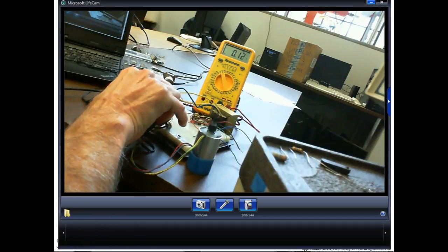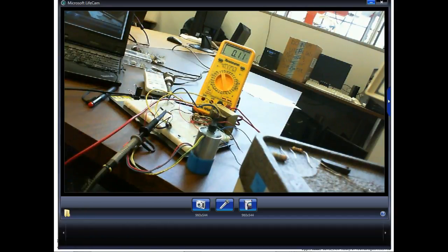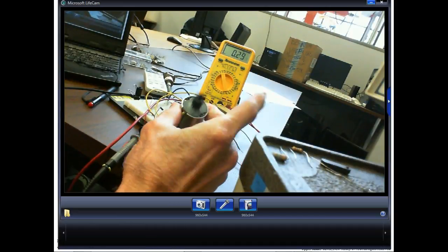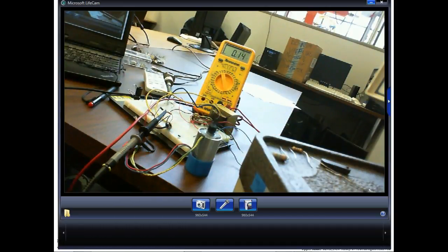It tries to. By the way, we got a motor called a universal motor. Guess what a universal motor will do? It'll run on AC or DC. It's a series motor for some reasons we're not going to talk about. But look here, that's running real nice. Make sure I have a 1 amp transformer, plenty to run this motor. Got a 1 amp diode, plenty to run the motor. If I put the little silver 914 that we passed around the other day, it'd probably burn it up.